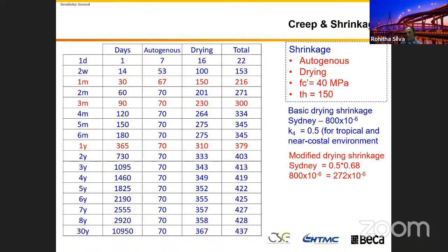The period you leave the girder after you cast it is going to affect us significantly, because we set the bridge alignment first. Based on that, we set all our levels, and we build the bridge from the bottom up. You do your pile footing, girder, bearing, all these levels we set, assuming this is the final finish level of the bridge.